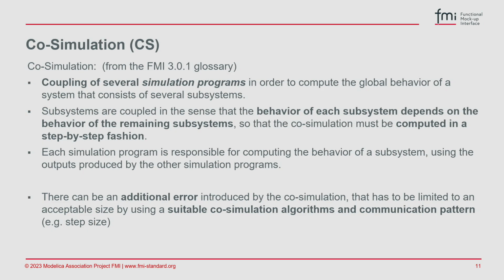But this is closely coupled, and you have to simulate it simultaneously, but the important thing is here that you don't expect it to be exact in the sense that it would give exactly the same behavior as if you would model it in one tool, but you can live with a certain kind of error, which you can influence by selecting a suitable orchestration algorithm, we call it co-simulation algorithm, and also designing a certain communication pattern, for example, selecting a suitable communication step between these submodels.